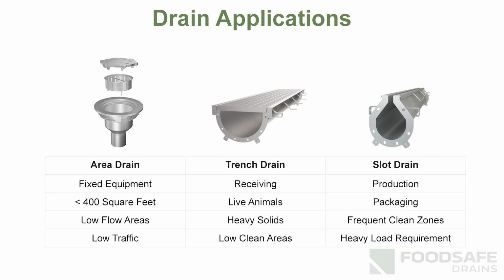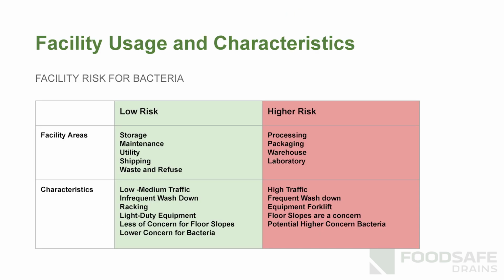If you need something to collect a lot of volume of water at once, like a kettle or something, or you want to collect solids, then trench drains are great, but you have to deal with the cleaning challenges. And then area drains are awesome, but they're really designed for small areas, not for mass use. So you're going to look at your facility from low to high risk and determine, where are we using stainless drains, where are we using cast iron drains, because you'll have both in any facility.